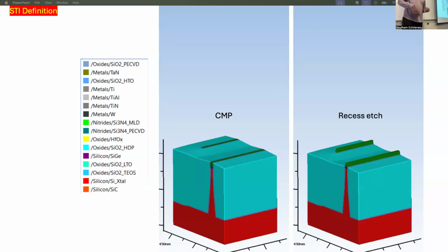Yeah. You do DOE, design of experiments. You do multiple runs with different etching times. So basically, if you're doing this in industry, you first try different etch rates, different etch times, different etch energies, and so on. And then every time, you take a cross section of the device, you do a FIB, and then you do an SEM to see how the profile looks. That's how you do it.